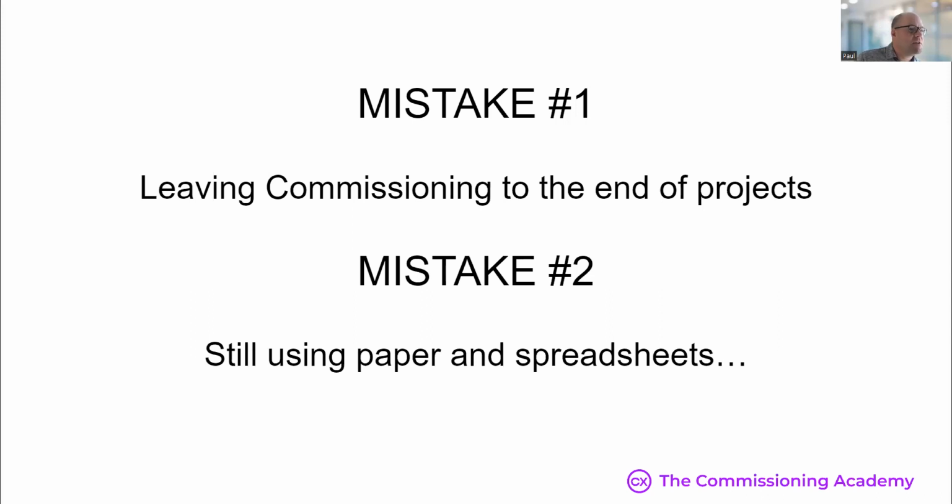Patrick, what change have you seen with commissioning in the past 4 years? 4 years ago, we used a paper startup checklist with a witness manual. Is there an electronic sign-off method for the checklist? Absolutely, and that's what the software does. There are always some instances on projects where you still need a paper process. If you're going into intrinsically safe areas, you still need a paperwork process, but we keep that to a minimum. And everything else that doesn't have those restrictions, it's all digital checklists. So your paper checklist is right in the software.